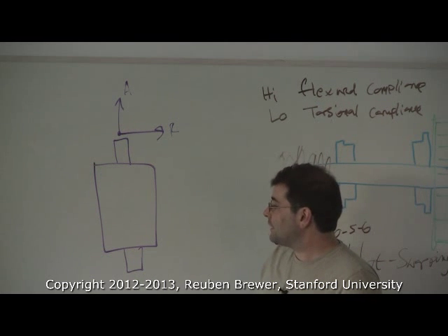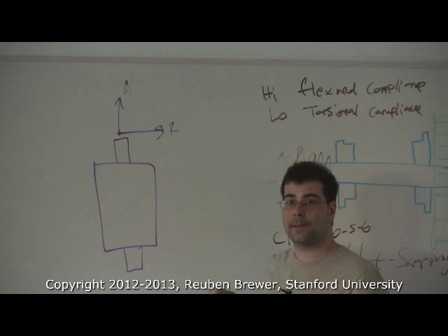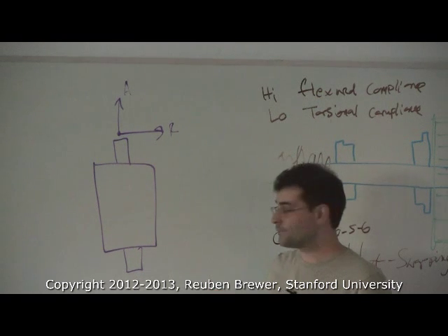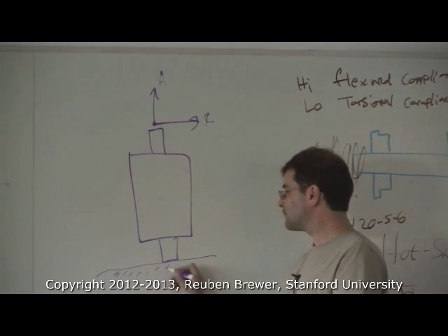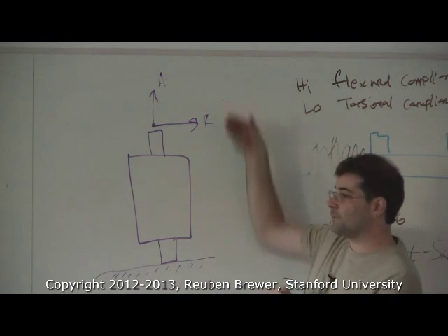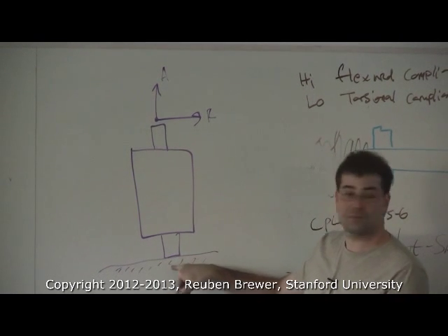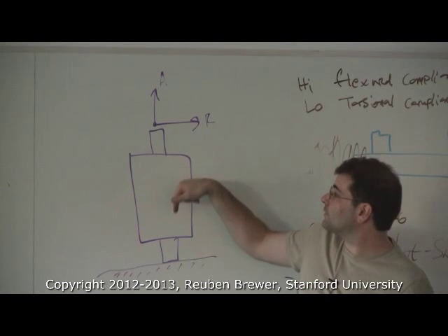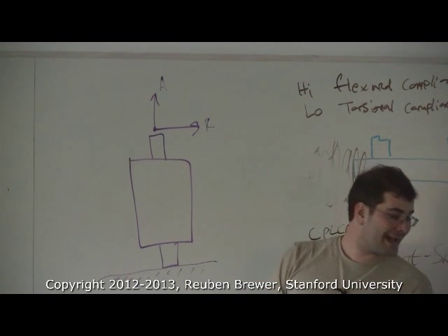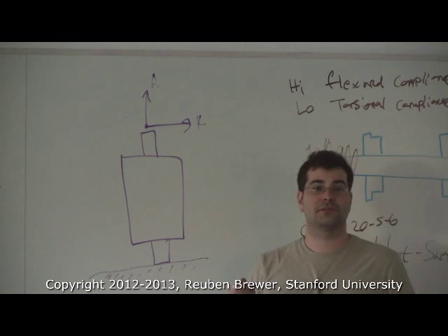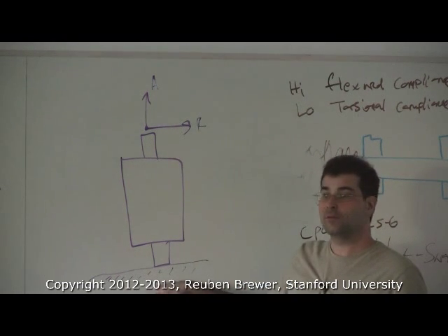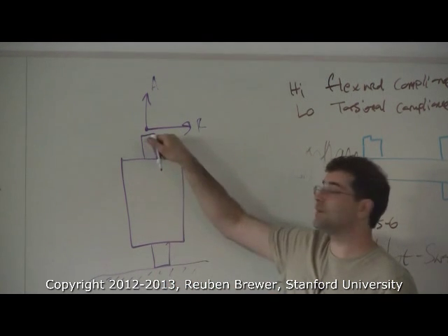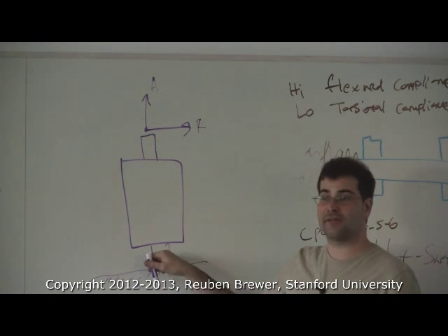Any clue how we could get past that? No? It says shaft supported. Why are we holding this mid-air while we press fit? If we put this on the ground and support the back shaft, then we can apply more load so we don't kill our bearings. The axial and radial loads are all about bearing loads. So if we actually support this so it's just one solid steel beam, we can have much higher press fit loads in axial.